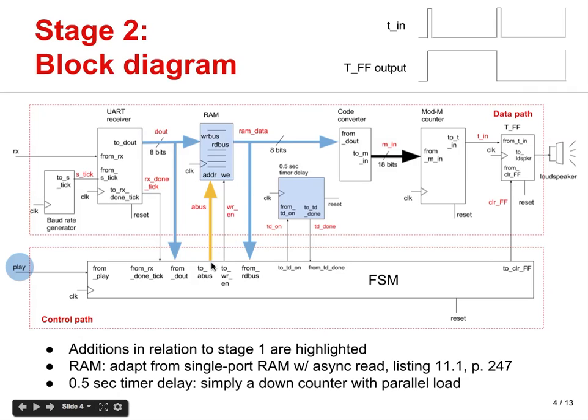Please bear in mind that for every input that comes into the control path, there will be one or more decision boxes in the corresponding ASMD chart. If by any chance, when you have designed the ASMD chart, you find out that some of these inputs have no corresponding decision box, then something is wrong. Either you had represented inputs that weren't really necessary, or otherwise you have forgotten to include some decision point in your ASMD chart.